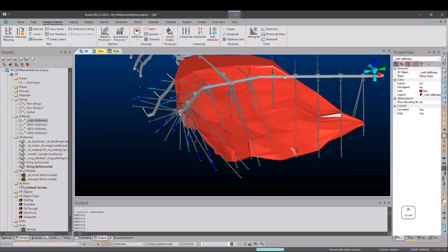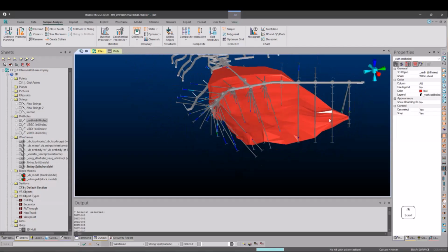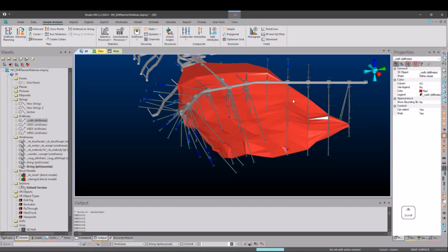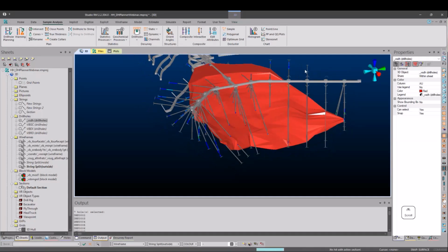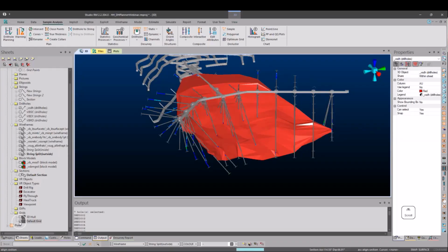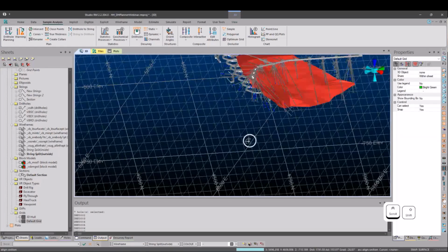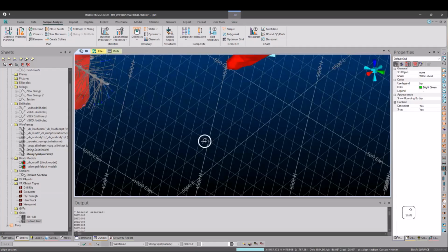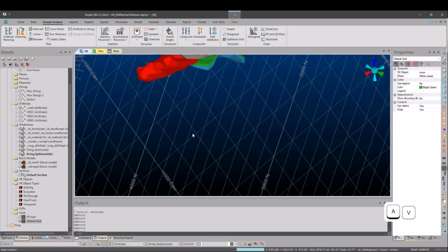I'm going to align it to the plane that's most representative of my pierce points. In this case, I'm going to use these because they're easy. They're a demo data set for a reason. I'm going to just set a section through here. And if you don't already know, whatever view you're on, you can set that as your active section through ASX or align section. When you turn on the grid, it's going to show you what view you're looking at. And if you rotate away, you can go back to it through AVW.